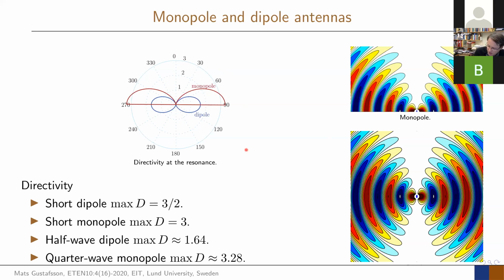And you can make an interpretation of this. If you think what's happening here, you have your monopole here. And the effective area is that a wave comes in to it. And of course, this wave can now come down and hit the ground plane and get reflected up. That's one way of thinking about it. And one part goes direct to it. And in some ways, you can absorb both of them. That is one simple picture. And the one that comes to the ground plane is the one that would hit the image currents. Okay. So they are changing in these cases.